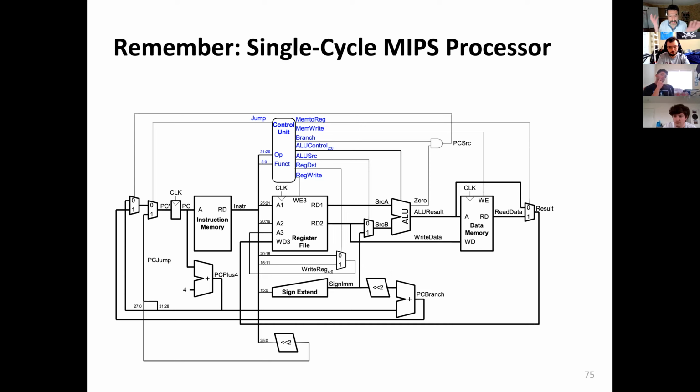So we add directly to the register file, and we are not violating the property by adding things to the register file, because the programmer sees the next state, sees this change to the register file. She doesn't see the changes between the clock cycle. After the clock has finished, she sees that this register has changed, even though maybe we wrote to the register file in the middle of the clock cycle. The effect will be observed by the programmer after the clock cycle has finished. And that's the property that we have.